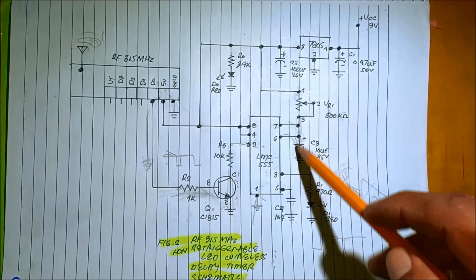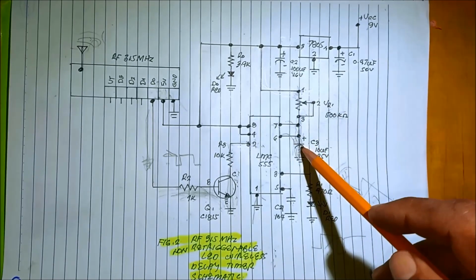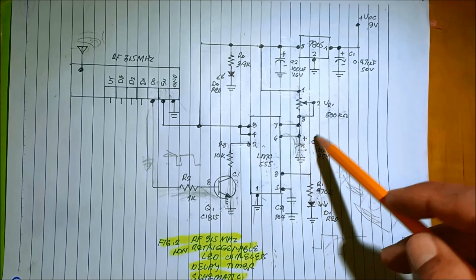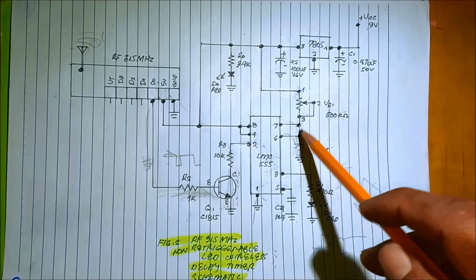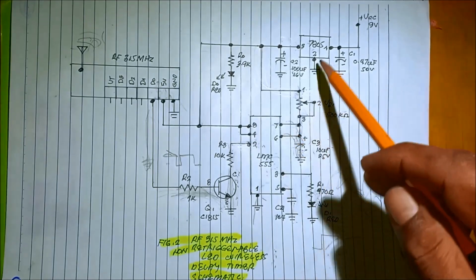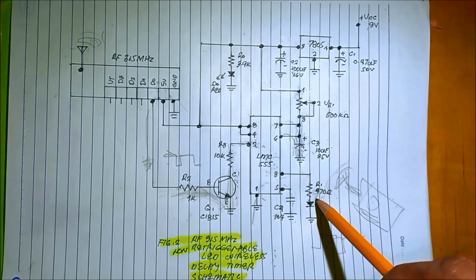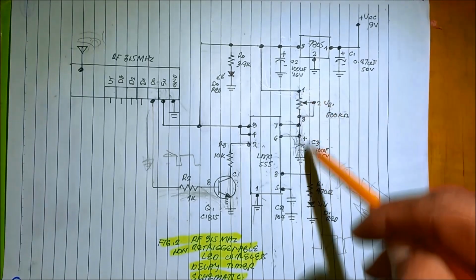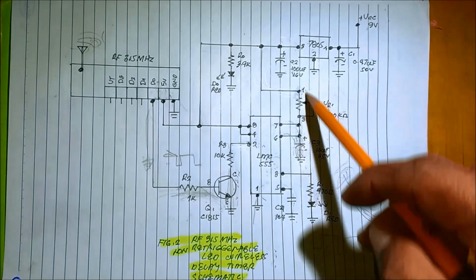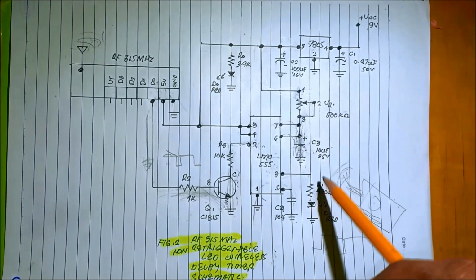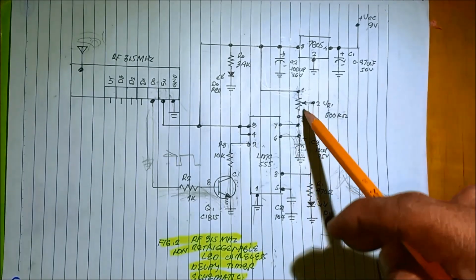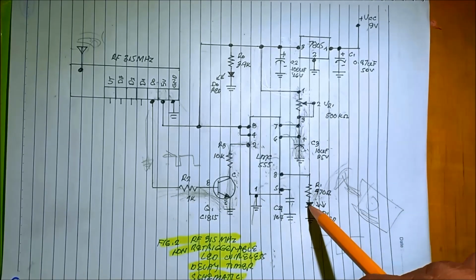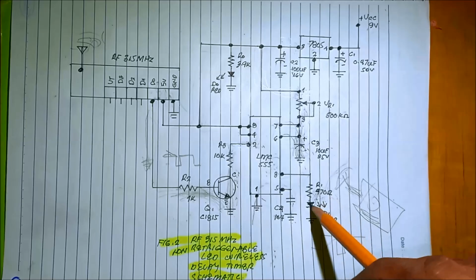And then there comes a time that the capacitor is charged to 2/3 of VCC. It will now go back to the initial state, and it will turn off the LED. So the two elements for the timing constant of the LED are the resistor and the capacitor. That's why the LED turns on and then turns off.